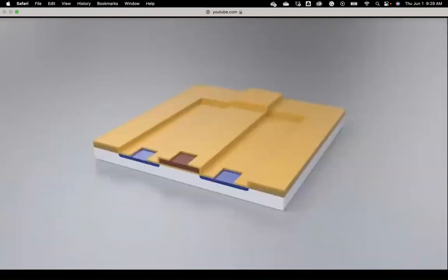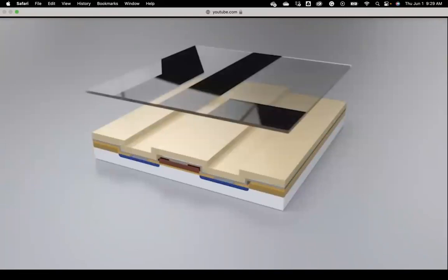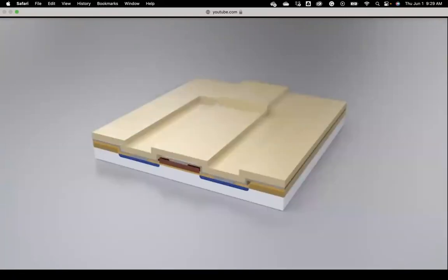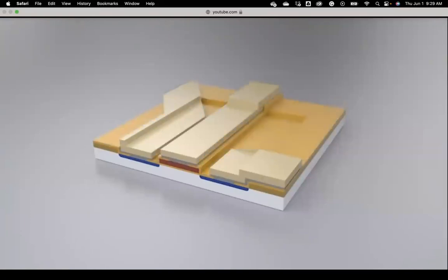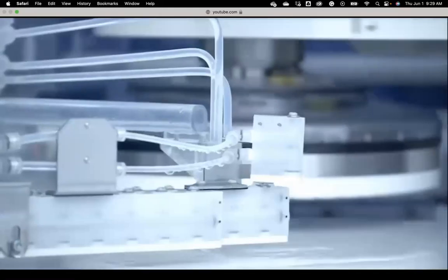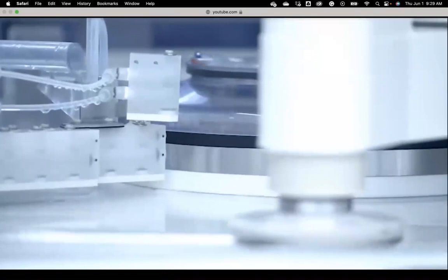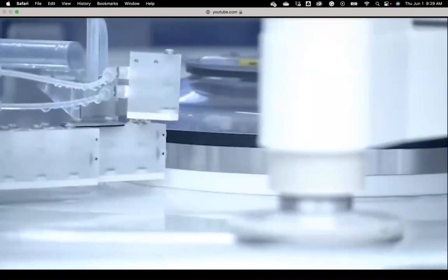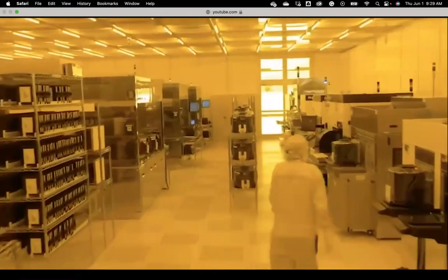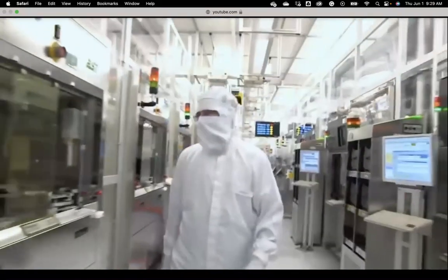Once again, the photoresist and mask are applied. The unexposed strips remain as is after the etching process, providing a point of contact to the underlying layers. To give the insulation layer above the interconnections the smooth finish it requires, a chemical-mechanical process is used to polish away excess material with micrometer accuracy. These individual steps may be repeated multiple times in the fabrication process until the integrated circuit is complete.